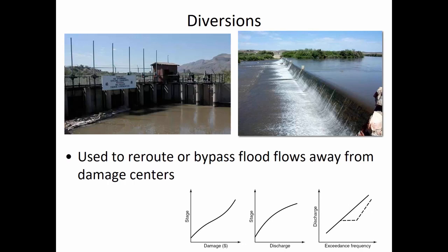So I guess what it says is that all of this is being rerouted, but once it begins to fail, then some of its previous capacity is lost. Once this gets to 26,000, then we still can't get 5,000 CFS through this channel. That would be the argument of what that graph is saying, that once you get beyond the capacity of the diversion, its capacity doesn't stay at its maximum, but is actually getting lower. I'm not sure, in the original channel. I don't know, you could argue that it would be flat.